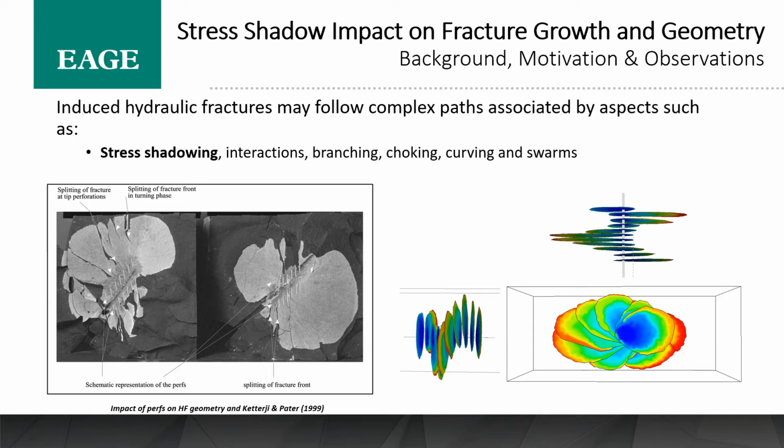on the left hand side, and this is really demonstrating from the well and the perforations how complex the fracture propagation can be. You're seeing splitting of a single fracture here. It's growing in different orientations. Some of the fractures are almost inhibited from further growth and you're getting some dominant ones. Quite a complex pattern you can see there.